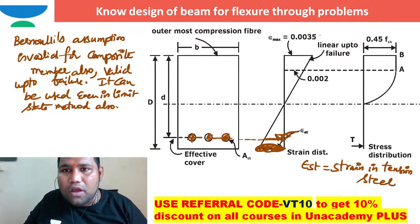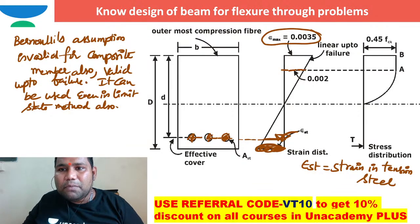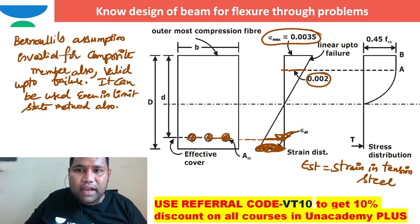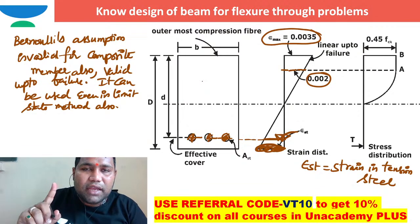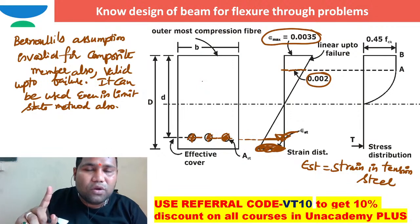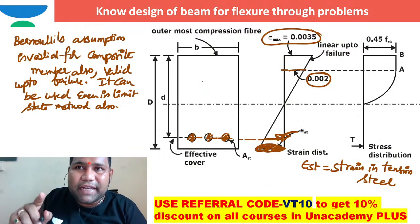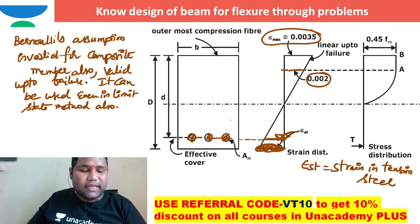I just need to mention why I am considering the maximum strain in concrete at extreme compression fiber as 0.002. What is this strain which is 0.002? I need to mention how I got these, and everybody knows why the strain is linear in fashion, right? And I just want to convey, especially in the limit state method or even in Euler-Bernoulli's theorem, that concrete is good in compression. Yes, concrete is weak in tension. The concrete which is in tension zone will not resist any sort of stresses, right?